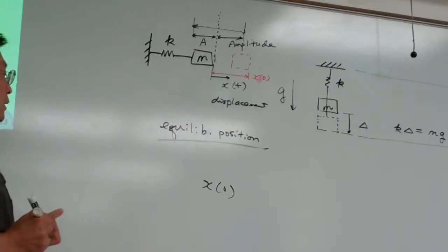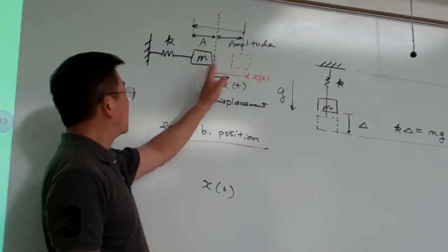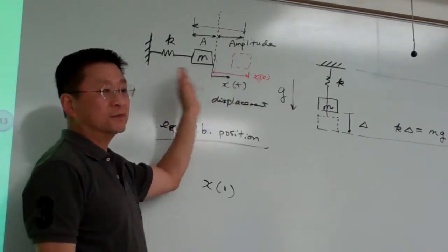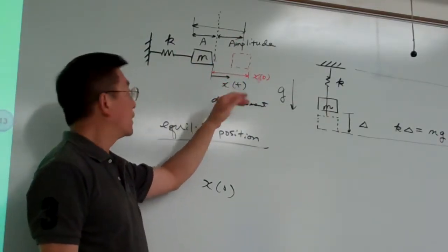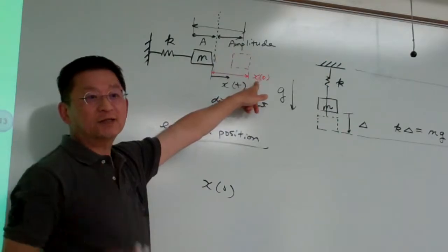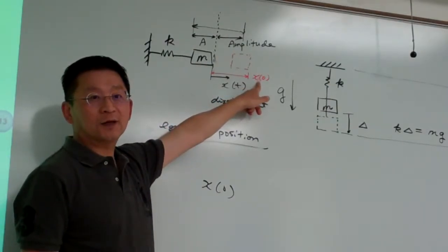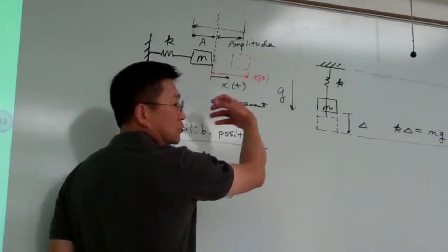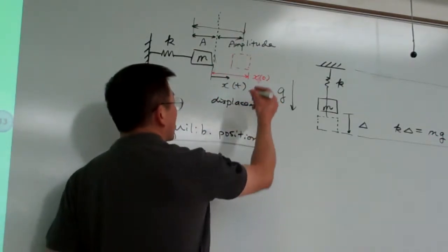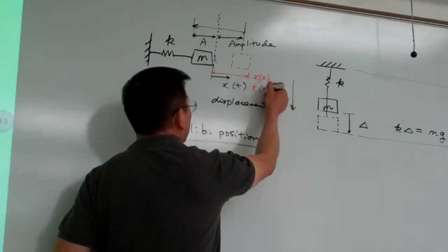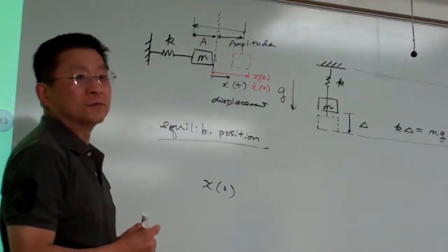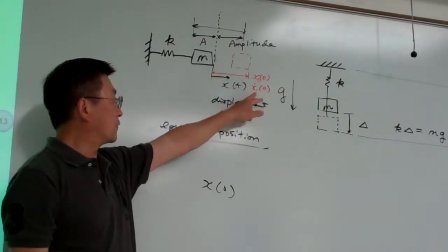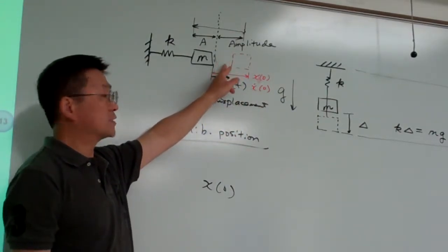Okay. So if you put this mass block to this position and you release it, then it's going to vibrate, going to oscillate. And this amount you can decide with the initial position. Even more general is this: you pull it so quickly that you also create a certain initial velocity. So in general, you can provide initial position and initial velocity to a vibrating system.